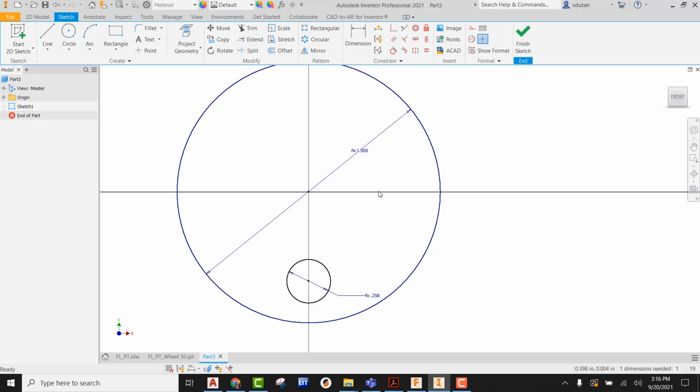So when looking at my dimension drawing reference sheet, it is saying that the dimension from the center point of our cam to the center point of our hole is going to be DIA times 0.25. Okay, it's going to be a quarter of the diameter all the time. And we can see how that slides right into place, and we're good to go. All right, so we're done with this.